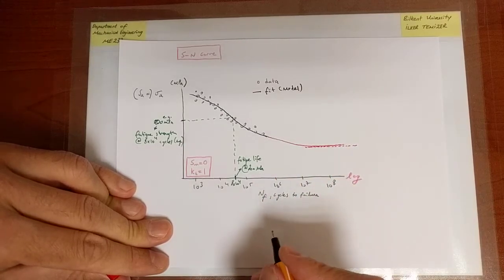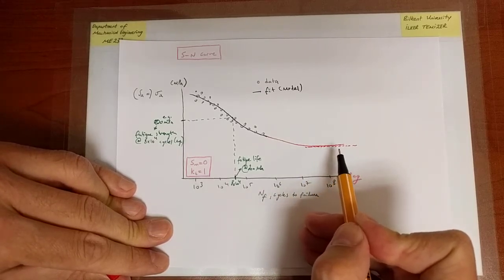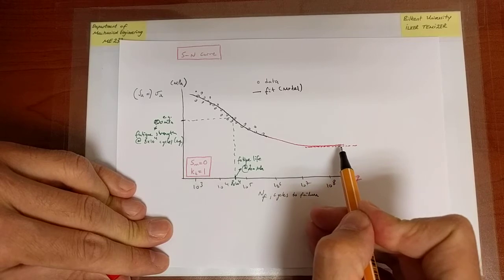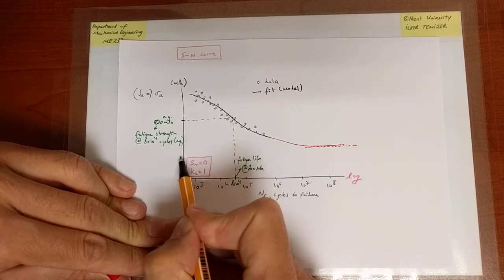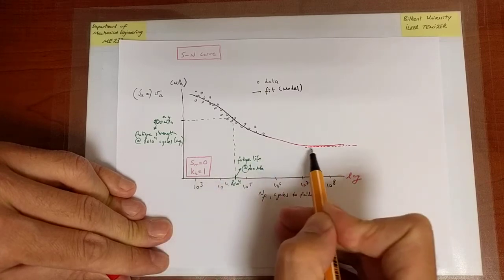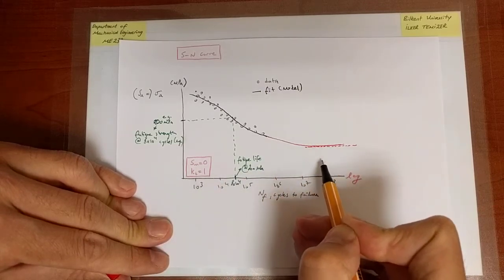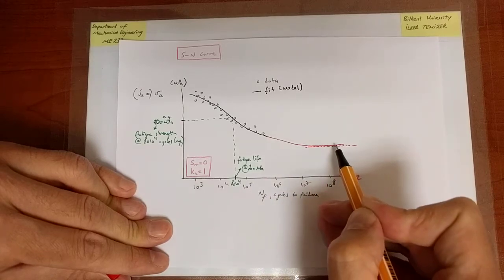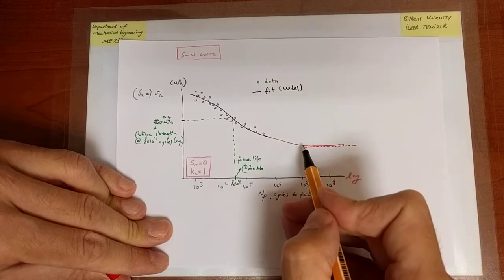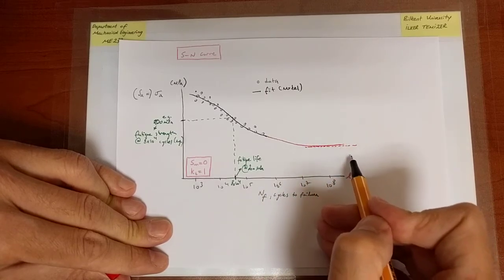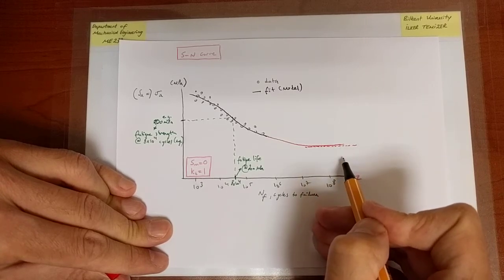We seem to observe that if the stress amplitude is below a certain value, then you never get fatigue. You can cycle forever, and you're not going to experience the structure breaking, because you don't have any data point for failure below that value of the stress.